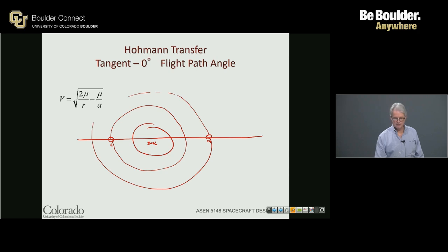And to have flight path angle on the Earth's circular orbit be exactly equal to 0 flight path angle on Mars orbit, and then we could leave Earth and arrive at Mars with the most optimum velocity changes, right? Velocity changes are optimal with 0 flight path angle, okay?